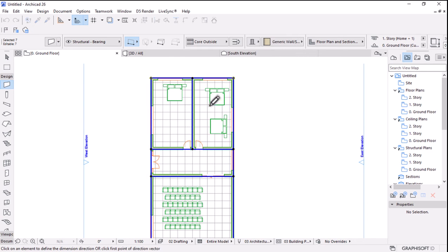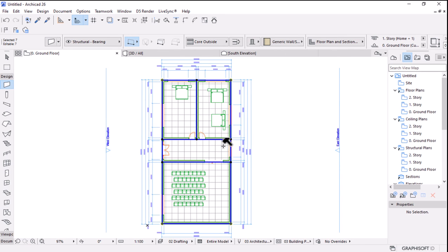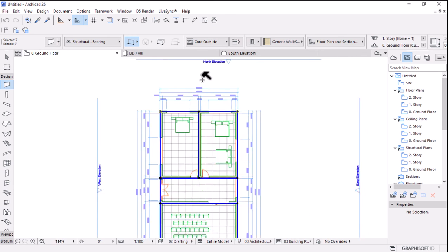Okay, this is the distance between the dimension rows, and this is basically a preview of all your dimension rows. So I'm gonna hit OK, and then once you hit OK, you have to draw the line indicating the length or the width of your building or your project, and then this hammer cursor will be active. You click outside relatively near the project like that. Boom, now you have all dimensions placed.